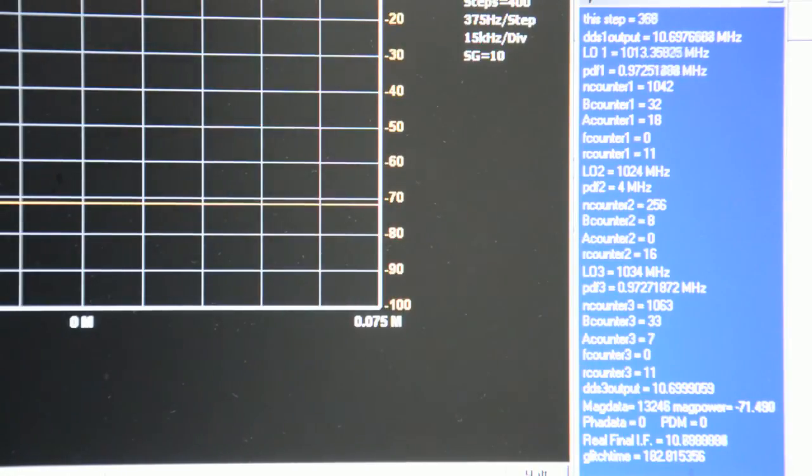But anyway, what I have now is I'm feeding 1 volt DC into the ADC, and I'm doing that because in theory I shouldn't measure any change in voltage whatsoever. Of course there is noise coming from the signal generator, noise being injected into the ADC, and so on, so that's not going to be the case, but it's actually pretty close.